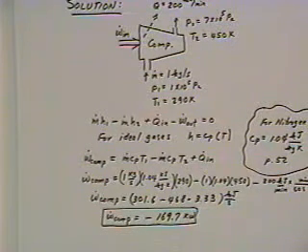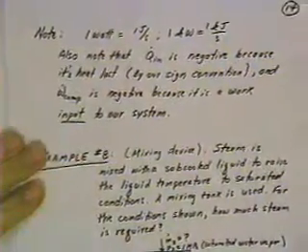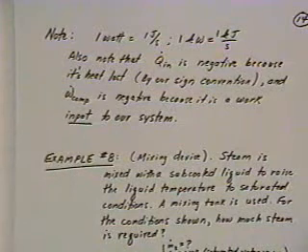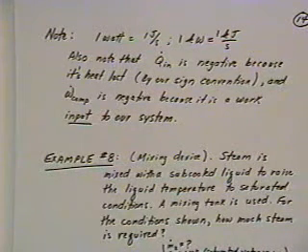That's the size of motor that you would have to have in order to accomplish this compression for a kilogram per second of nitrogen, which is a pretty heavy load and quite a lot of compression that would be required to do that. Now, a couple things that I'd like to remind you of on the expression here that we just found. That is, a watt is 1 joule per second, so therefore 1 kilowatt is 1 kilojoule per second.